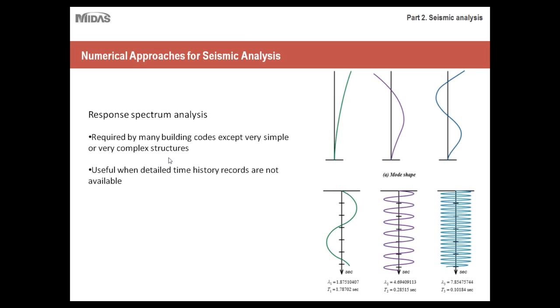and you would use those time history records in your analysis. I'll go into greater detail about this later, but just keep in mind that with response spectrum analysis, you don't need these time history records. You can work without them. That's particularly useful because using those time history records and implementing them is very time-consuming. It's a very detailed process.